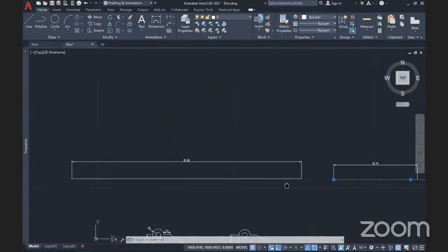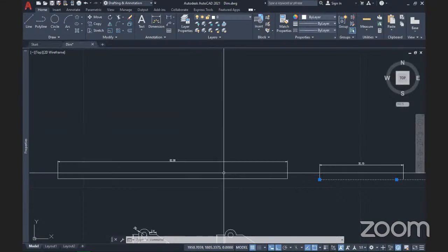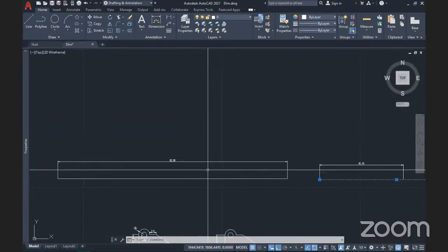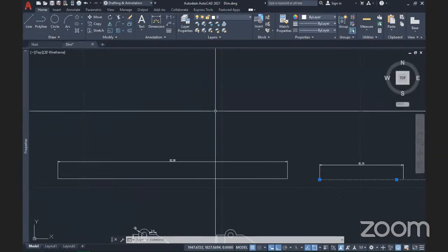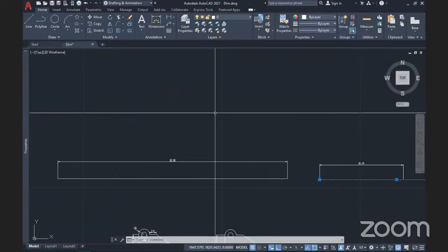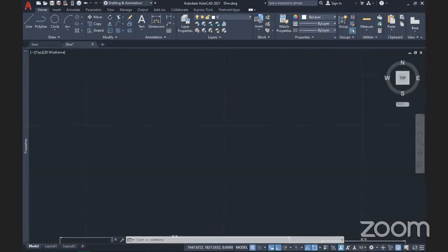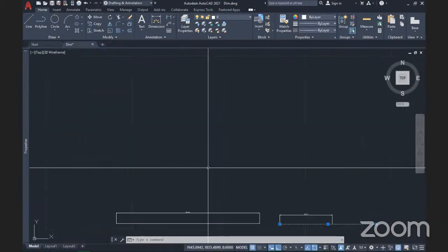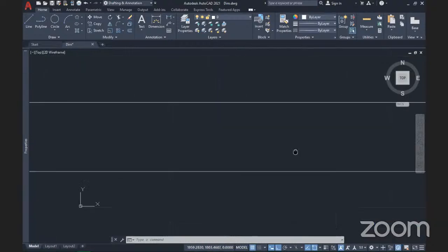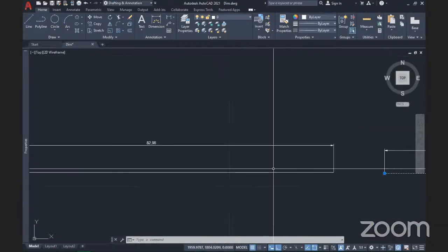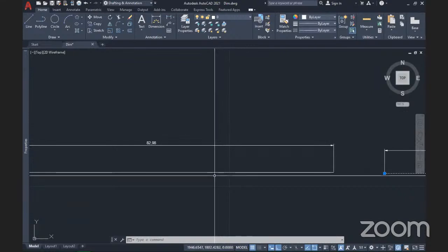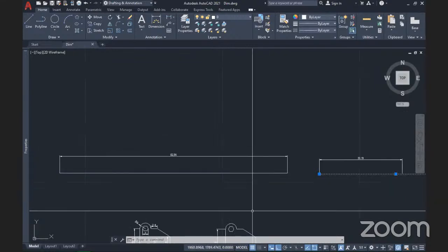So what I did was, like I said, you can create two types of dimensions, just like in arrays where some of them are associated and some of them are not associated. So you can create a dimension that is associated with the particular object created. In this case, I created an object and I associated the dimension with that object by using the DIMASSOC command, D-I-M-A-S-S-O-C.